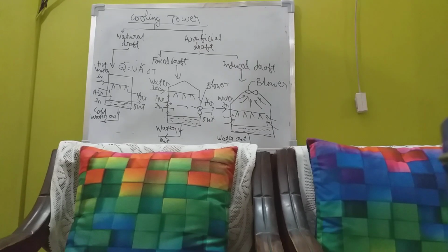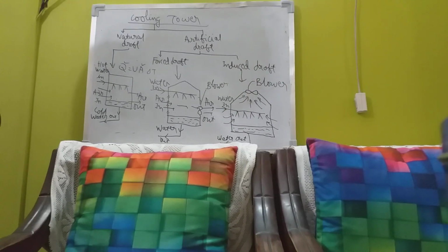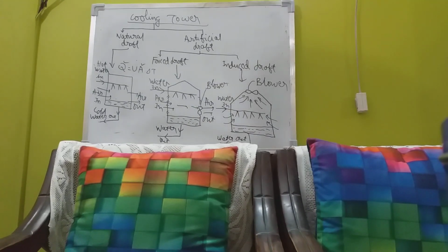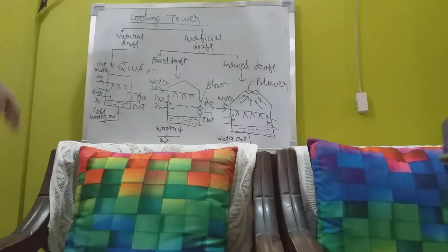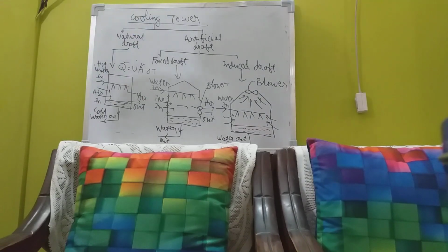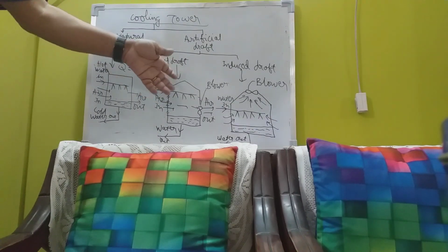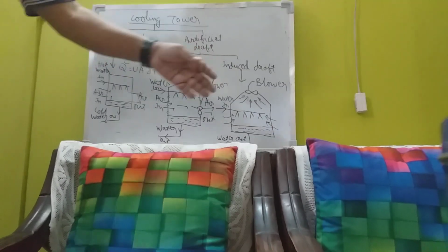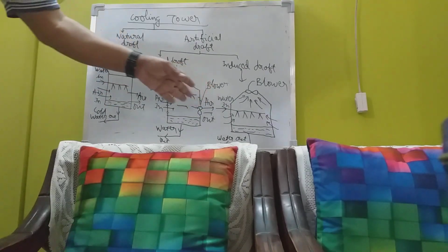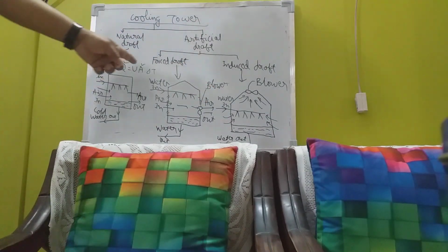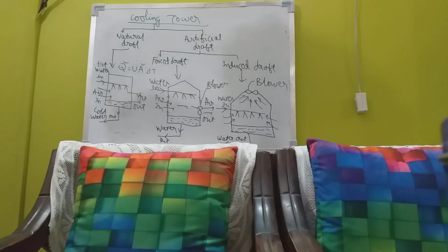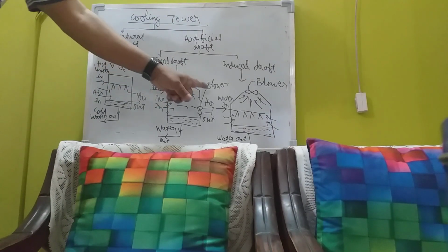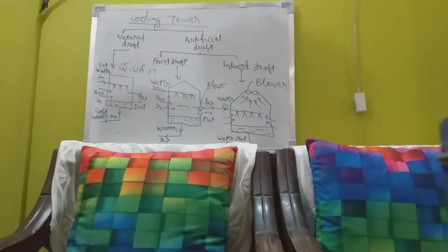Especially when you place it on the rooftop, there will be water tanks, electrical panels, and so many other things in the rooftop. And you don't get a clear space. And when you don't get a clear space in the rooftop, naturally the circulation of air is not proper. And if air circulation is not proper, the cooling will be less. The efficiency of the cooling tower will be affected. So this type of cooling tower is not generally preferred much.